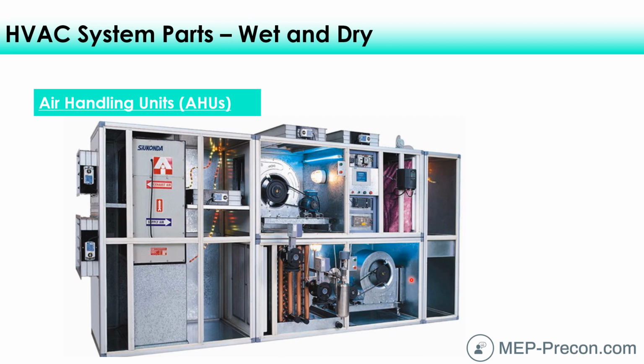And then we have another fan here, and it looks like, to save space, this is kind of a double-decker air handler. Most of them are just kind of a single tunnel, but this is kind of a dual tunnel. It's going to go over here and go up, and then kind of come back through maybe a set of final filters. So maybe this is for some really clean operation, maybe for a hospital or something. And it's going to turn again and go up through here, out this outlet. And notice we have some actuators on these little dampers here to control them for a variety of means here.